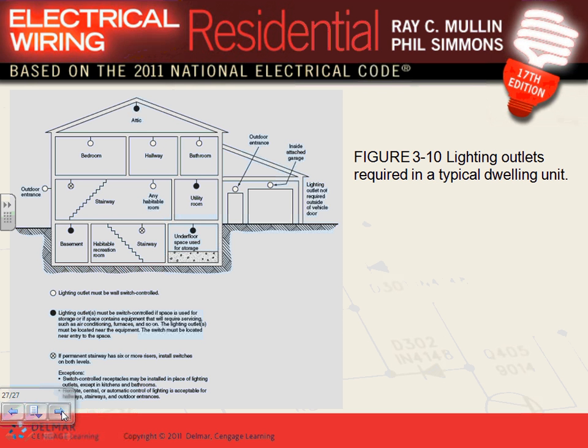Okay, lights. Any question about receptacles? That will cover almost all the receptacles that we do. I have a few minutes before I let you guys go. For any question about receptacles in residential, and circuiting, we know how many, nine on every circuit, convenient, and lights separate from receptacles. We're going to have a 20 amp circuit for the kitchen, one for the bathroom, and one for the laundry. Everything else is going to be 15 amp circuits.